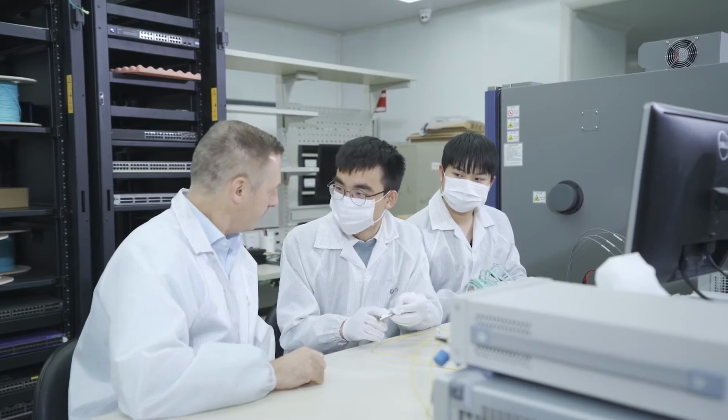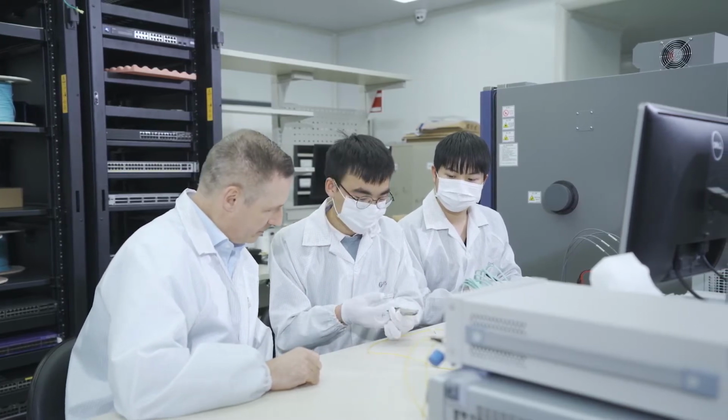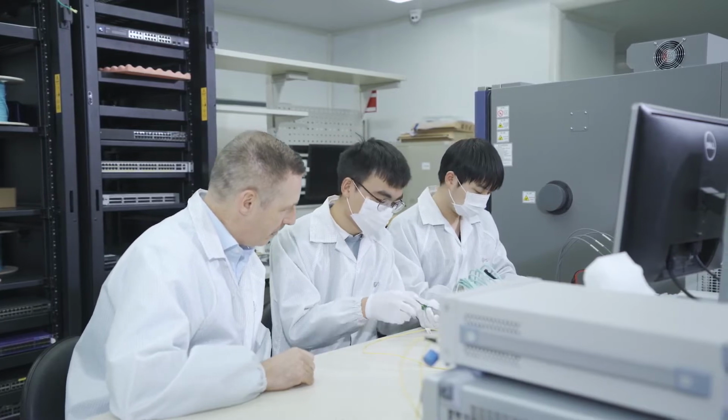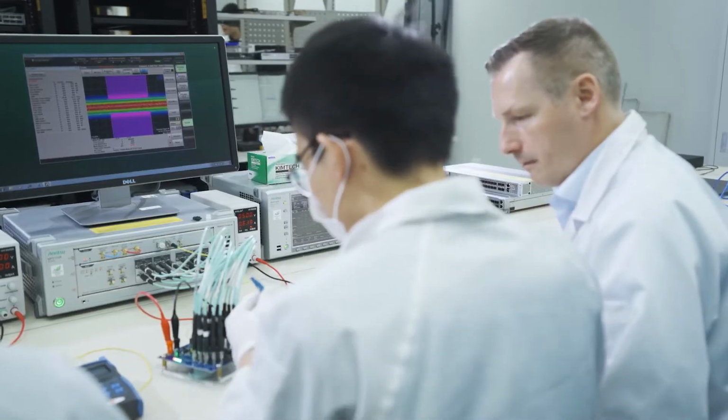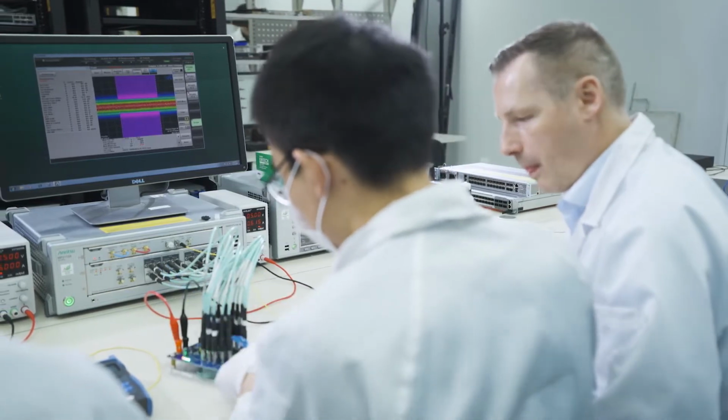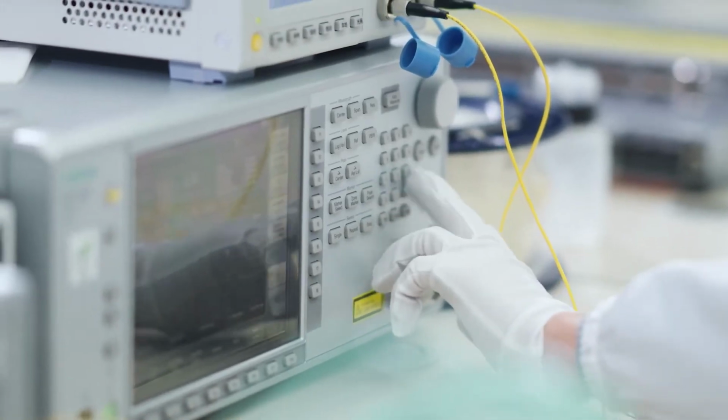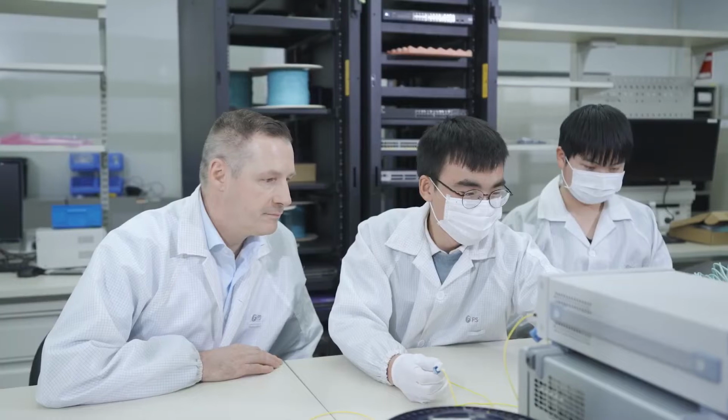Extinction ratio is an important and the most difficult indicator to measure the performance of 400 gigabit optical transceivers. FS conducts a performance test to check whether a laser works at the best bias point and within the optimal modulation efficiency range. The optical modulation amplitude can measure the power differences when the transceiver laser turns on and off, testing 400 gigabit transceivers' performance in another aspect.